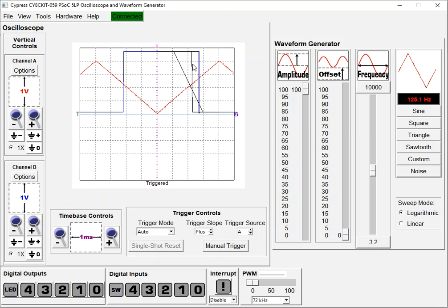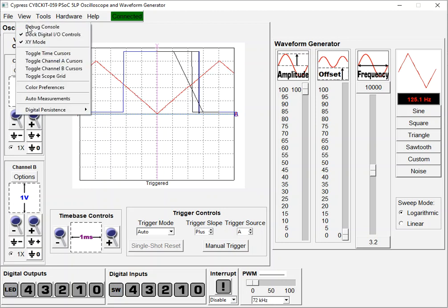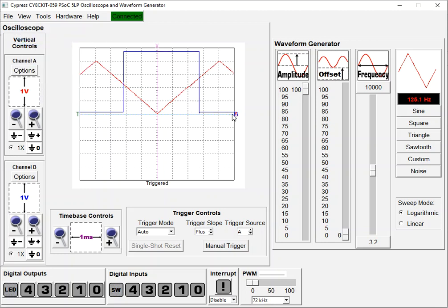So just looking at the volts per division, right? Normally the x-axis is time, but because we're doing XY mode, it's 1 volt per division, 1 volt per division, and it's kind of looking like it's half a volt, right? I can try to get a better estimate than that. I'll just turn off XY mode, and I need to zoom in on the voltage axis. So now I could kind of do it from here.